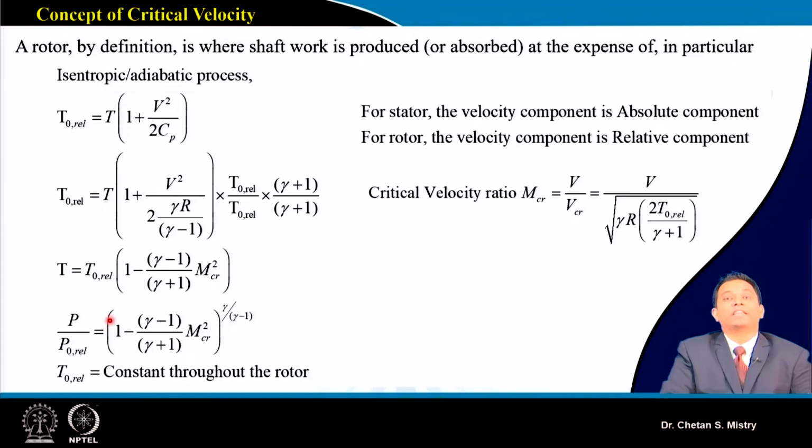One we can call the sizing problem. When we say it's a sizing problem, it means you are given some input parameters: your entry condition, the rotational speed, and the pressure rise you are expecting. And for that we will do our design for rotor and stator.